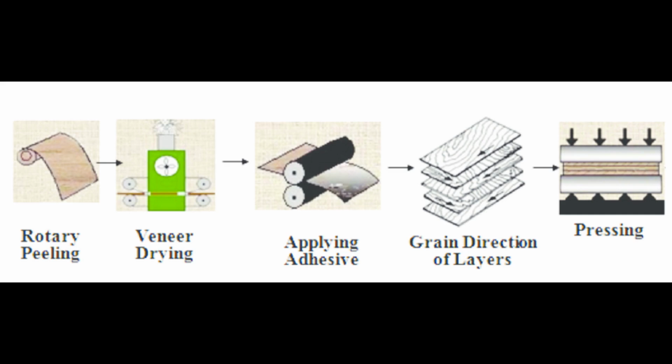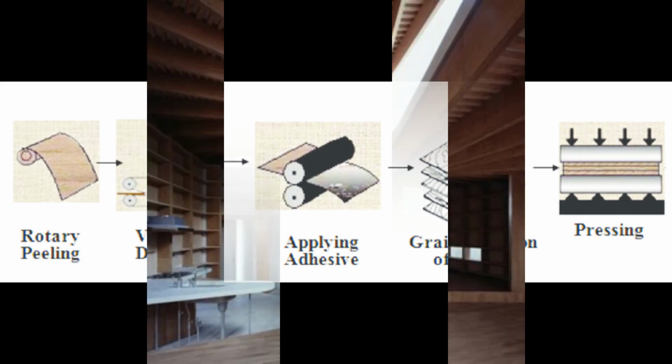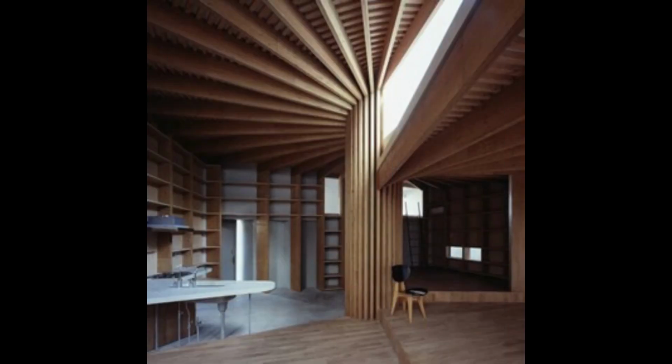Now let's see some applications of this plywood. Plywood is used in many applications that need high quality, high strength sheet material. Quality in this context means resistance to cracking, breaking, shrinkage, twisting, and warping. Exterior glued plywood is suitable for outdoor use, but because moisture affects the strength of wood, optimal performance is achieved where the moisture content remains relatively low.